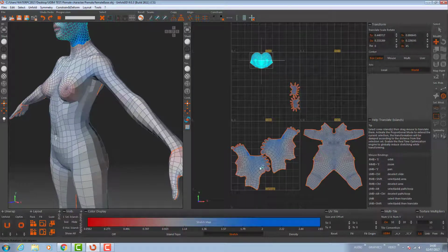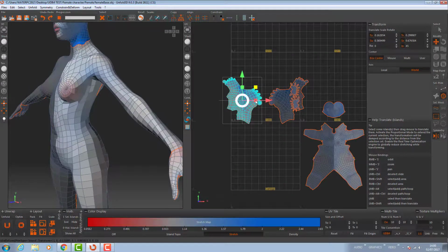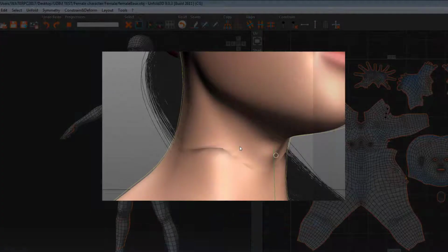During the modelling process, we would do well to think ahead where our seams are going to be and where we're going to be cutting them to get the best UV map. We do this because at times these seams can produce render artifacts. For this reason, we want to try to choose seams on the model where they are hidden, such as under the armpit of the character or down the inner seams of the legs.